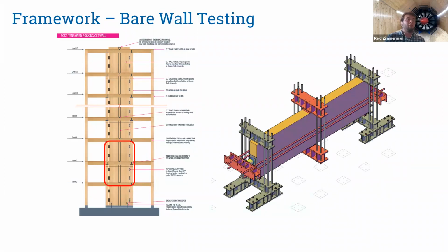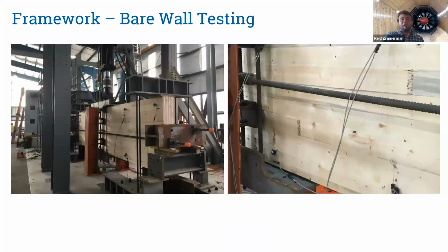So a lot of research has gone into out-of-plane stiffness, flexure and shear, rolling shear of CLT panels, but not as much on in-plane stiffness. So we worked with Oregon State University to devise a test setup that's shown here, and take CLT9 panels and put them in 3-point bending and cycle them. And in that way, be able to measure what the real shear stiffness is, which is a surprisingly tricky thing.